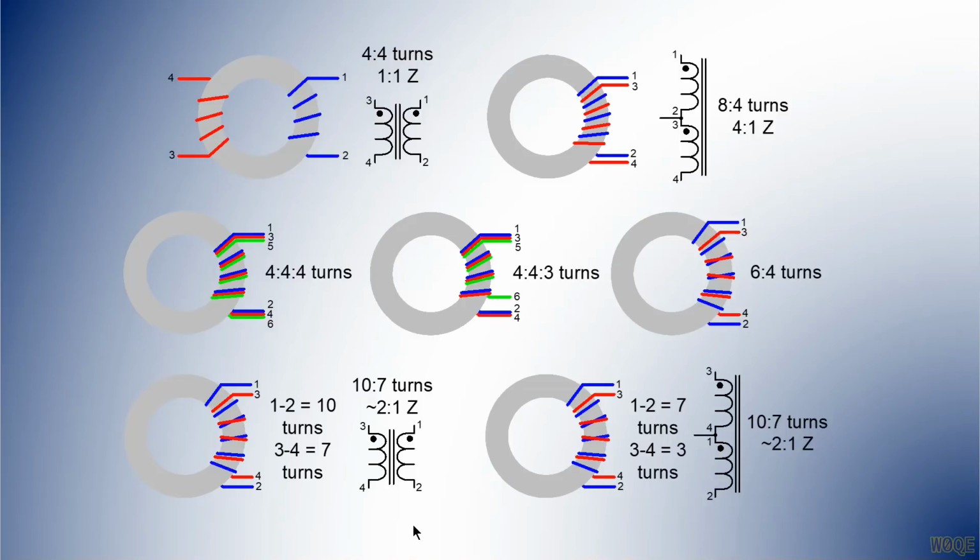Most designs desire a high coefficient of coupling. If you look at any commercial designs, coefficient of coupling almost is never good enough, and there's almost always some kind of a circuit compensation involved also, beside trying to get good coefficient of coupling. Without good coefficient of coupling, you can't really make the circuit work really, really well, but compensation definitely is a big help.